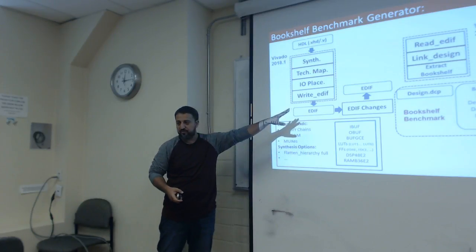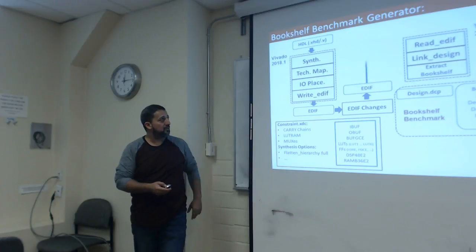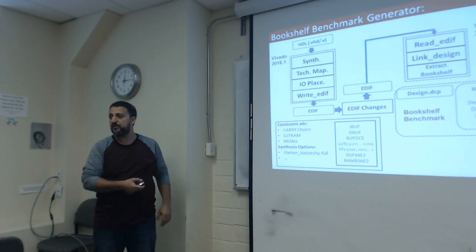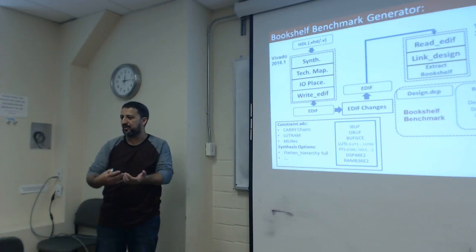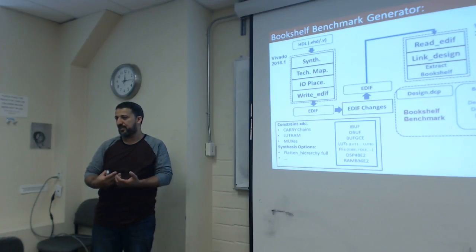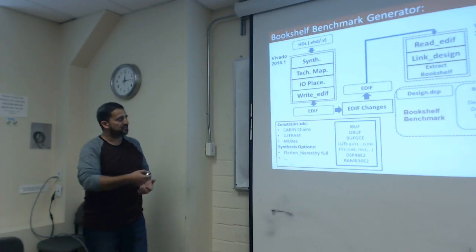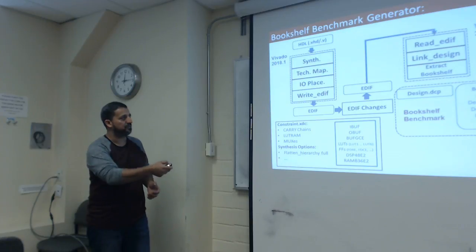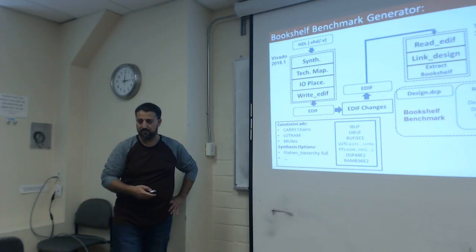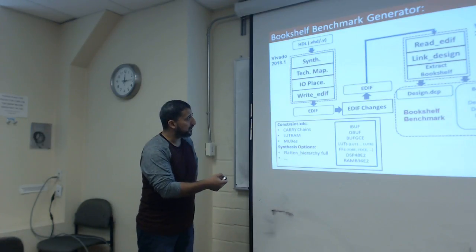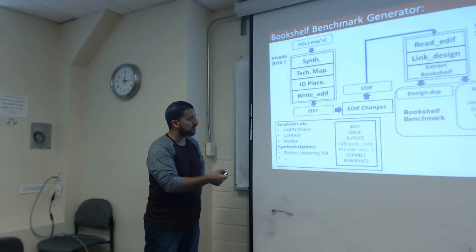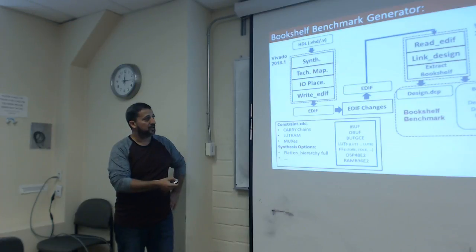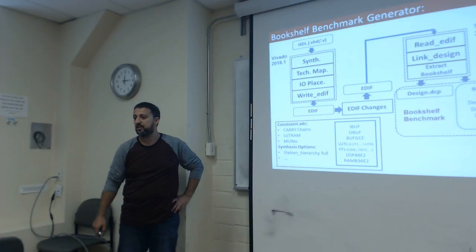We do this modification here, and then we read it into Vivado. Why Vivado 15.4? Because we have the patch to read and write to those academic placers. But we can easily later have this patch for the new Vivado, so we get rid of this old flow. And then we write a Tcl script that, after you read the design in the old Vivado, extracts the bookshelf as well as the checkpoint.